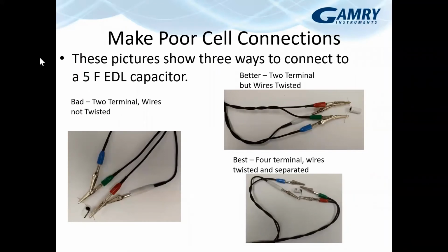So there are three different ways here to connect a capacitor. This is the worst of the group. This is using our 4-terminal device as a 2-terminal device. We've got our sense and force leads shorted together before they make contact with our wire. Also, everything is running in together, kind of parallel. This is as bad as it can get.